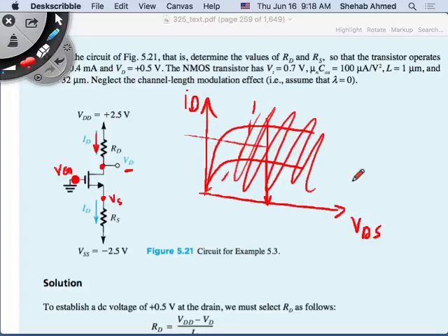So we had VG here at 0 volts, and S here at minus 1.2 volts, and D here at, I don't remember, 0.5 volts. So we had the various voltage levels. We know that the difference between these two to operate in saturation is what? The gate voltage is higher than my threshold voltage by an over voltage. So I have a threshold voltage and I have an over voltage, sort of here.